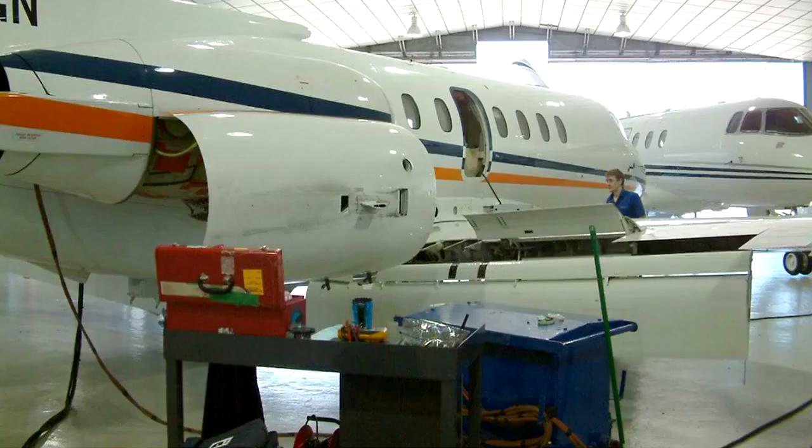On-condition maintenance is also a preventative primary maintenance process. It requires that an appliance or part be periodically inspected or checked against some appropriate physical standard to determine whether it can continue in service. The purpose of the standard is to remove the unit from service before failure during normal operation occurs.